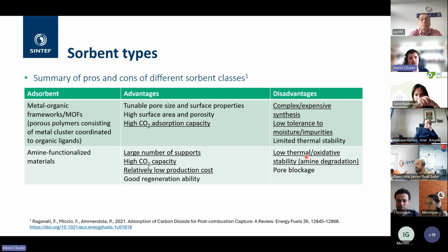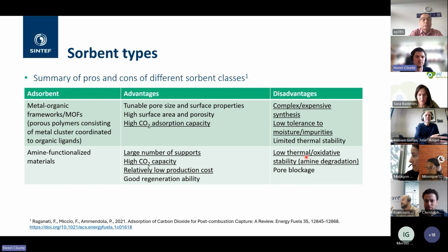Then there's also a lot of work on metal organic frameworks or MOFs, which again, for people not from a materials background, are porous polymers consisting of metal clusters that are linked with organic ligands, which can give you very nice structures that lead to very high surface areas, and you can tune the properties of your adsorption process basically with it. So this allows you to get very high CO2 adsorption capacities, but these materials are also a lot more expensive